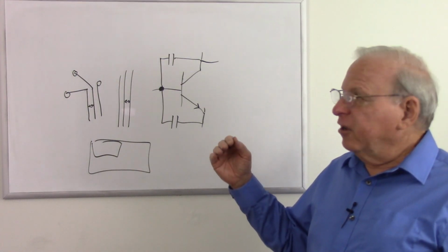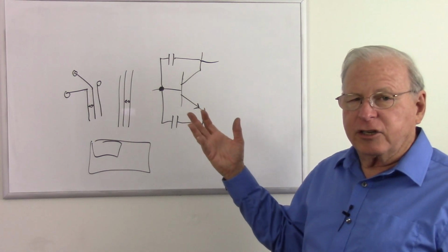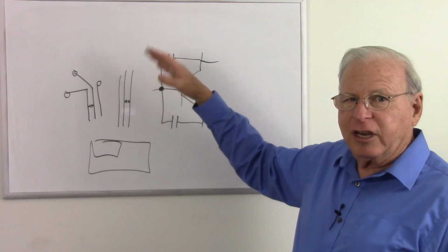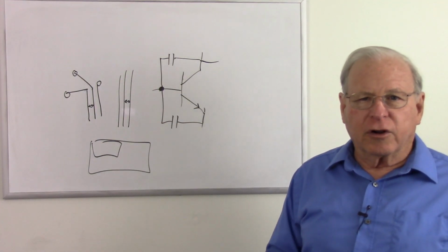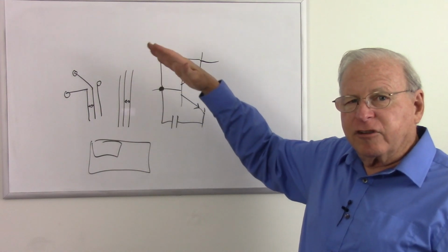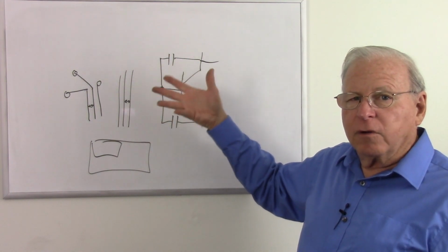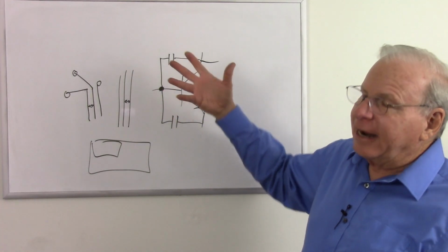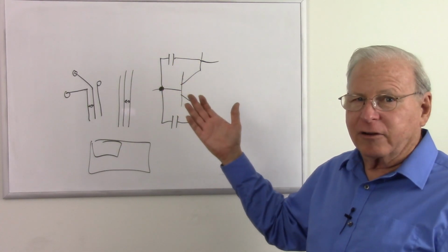Then we have analog circuits that do have a periodic change, such as audio circuits, like my signal from my microphone. We get vibrations anywhere from 20 hertz to 20 kilohertz, and circuits designed to work with those frequencies. And of course, those oscillations stay between the voltage limits. And when we talk about amplifiers, we'll see what problems happen if we get out of those limits. We get what's called harmonic distortion.